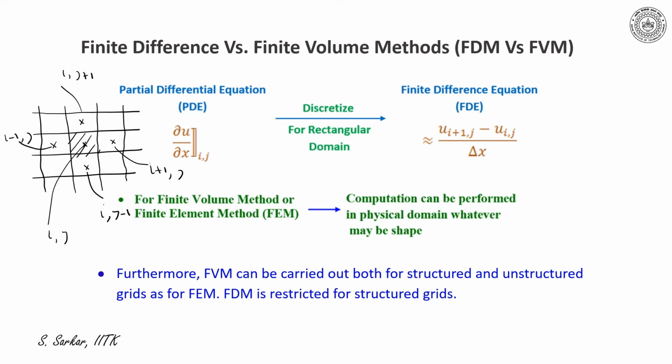Now for a structured mesh, which is represented here, the cell and the nodes are explicitly defined. Here the node is the point where the variable would be stored. In this case, the center is the node. So please note that for structured mesh, cell and nodes are explicitly defined.